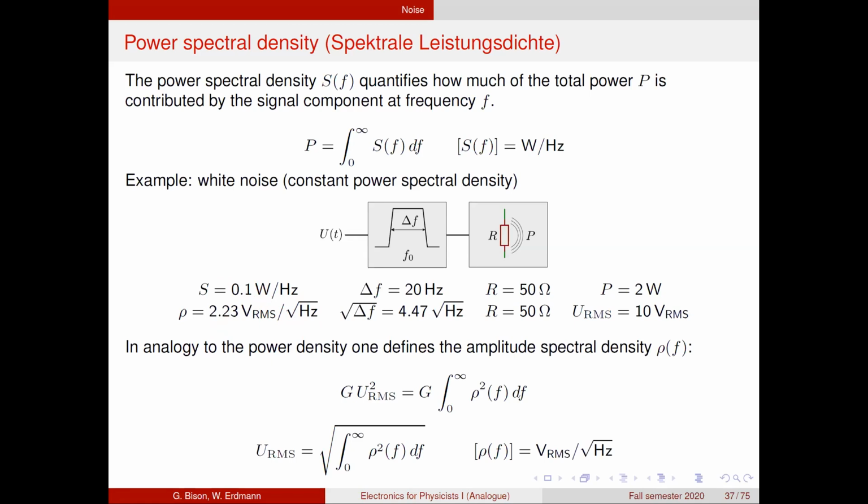One example is if we want to compute, from an RMS noise voltage, the spectral density. We could take the correct way and convert this RMS voltage into a power. Then we have to know what the resistor is in the system. Then we divide the power by the bandwidth and arrive at the spectral density.